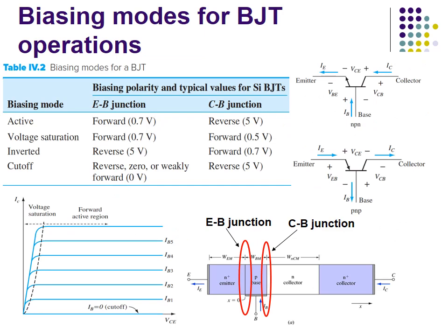We have mentioned that there are three operation modes for BJT: active, saturation, and cutoff. Under active mode, the BJT functions as an amplifier. To make the BJT operate in active mode, the emitter base junction must be in forward bias and the collector base junction in reverse bias.